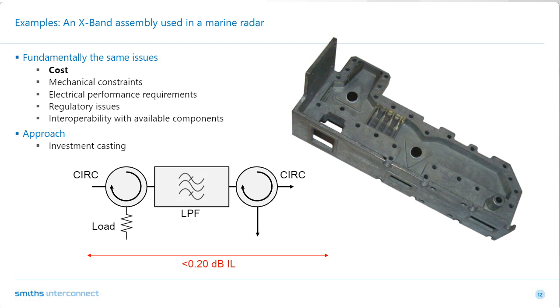What we had here, it may not be obvious to the eye, but the main point is that the circuitry was put into a package, and the package was not a machined part; it was cast. Because we had the quantities necessary, being able to have this housing cast versus machined drove down the costs and was a huge factor for our user. Moving on.